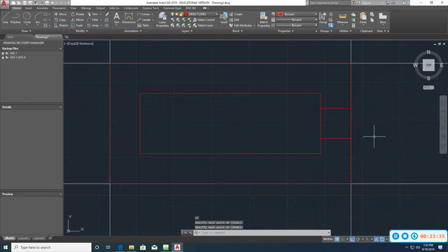Okay, I'm going to stop for a second until you catch up with me. No, we got the cutout in the top too. So how far from this corner right here is my cutout? From this corner here. It's 30, right? And it says 2 places. So what that means is it's going to be 30 from this edge and 30 from this edge. So let's do that. So I'm going to offset 30 from here and also from here. Enter. Now I got to trim this up, right? Trim.